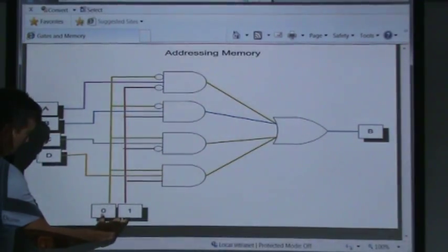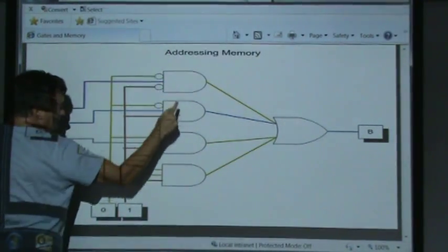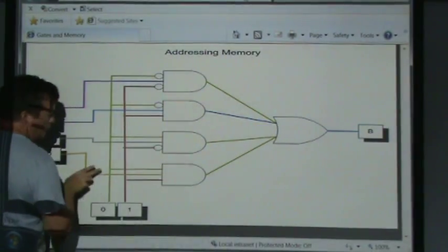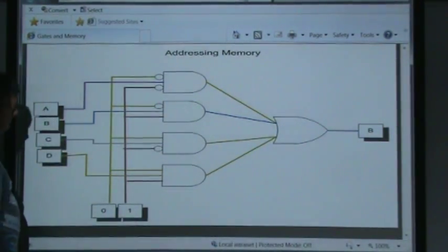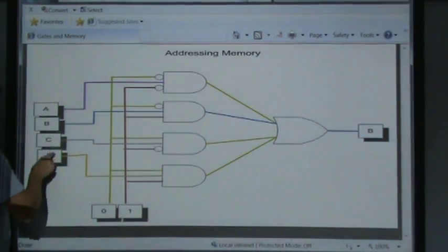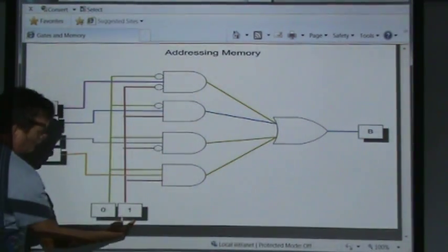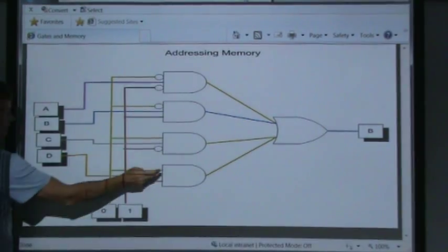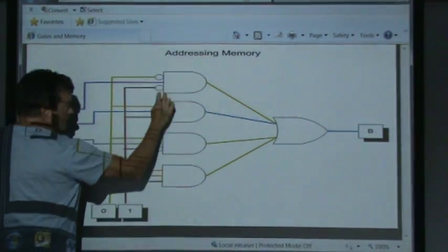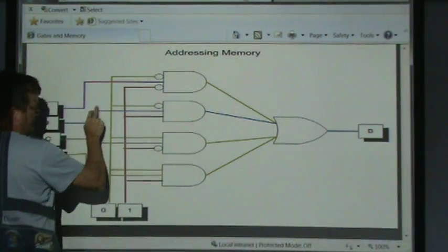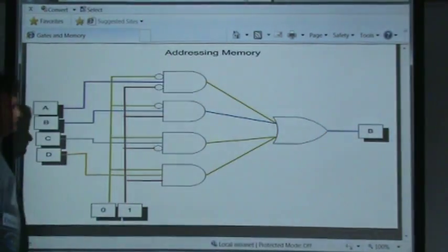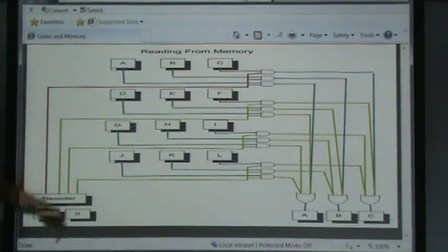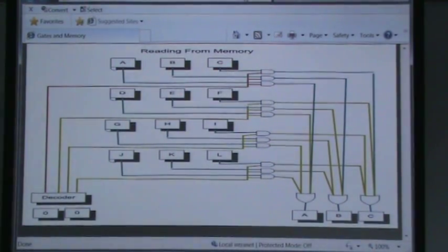This setting here caused this gate, and this gate to all output zeros. So what we really did was, out of these 4 inputs going into these 4 gates, with this value we shut off 3 of them, this one, and this one, and only left this one open, and that's how this value got traveled through and all of these got ORed together. So the 3 zeros and the blue line got ORed together.